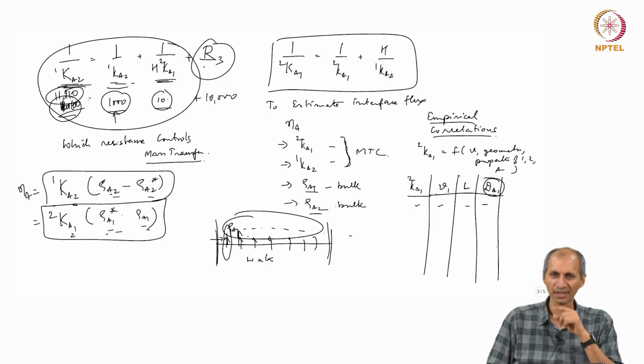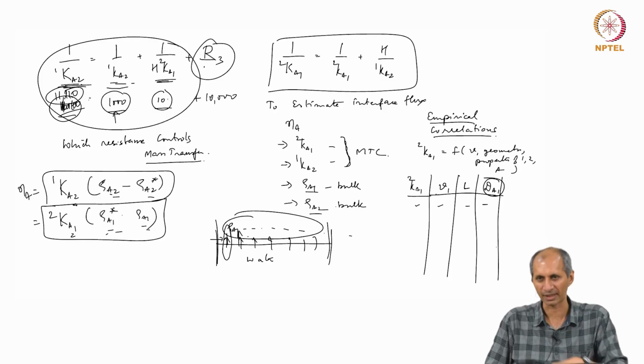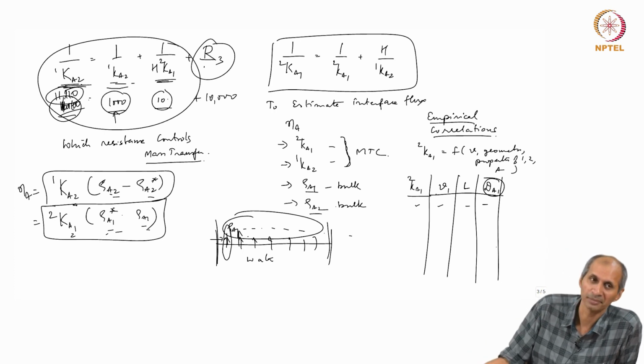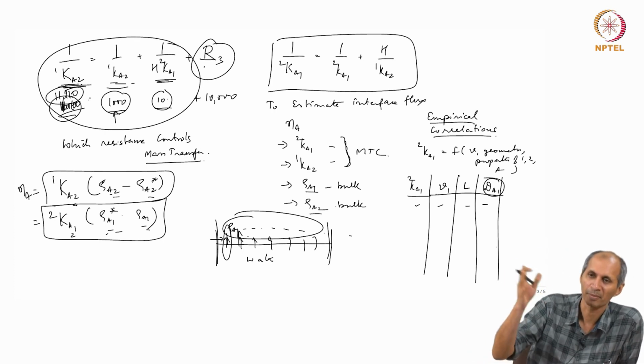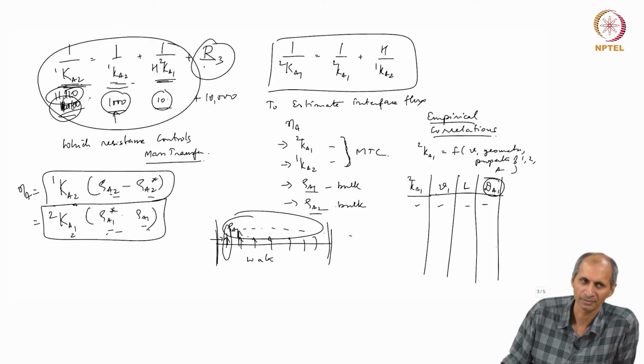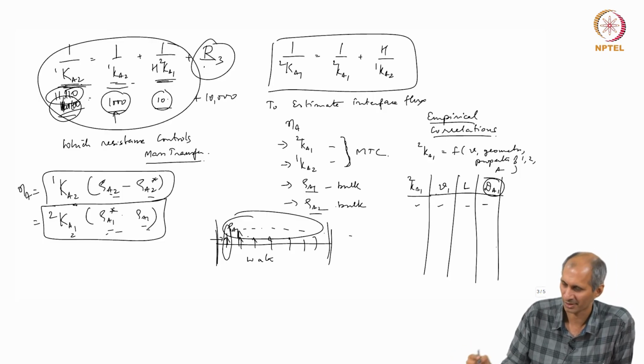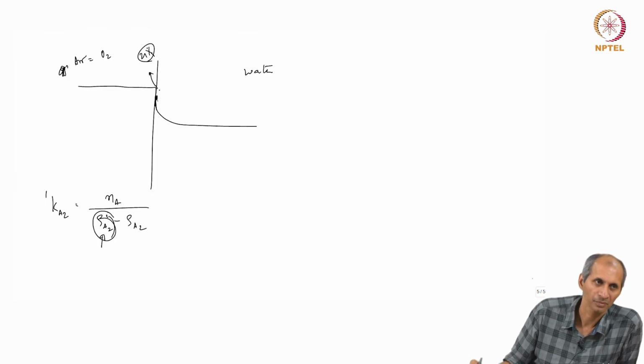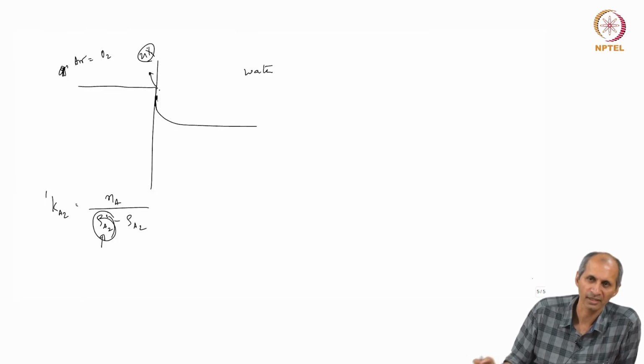Now, how do you convert a mass transfer coefficient that is measured with water and oxygen to some other vapor? Say I want to use it for benzene or some vapor phase chemical which wants to get in. How do we do that? It's a relevant question. Depending upon the molecular weight it can. So, we scale it like what we said yesterday.